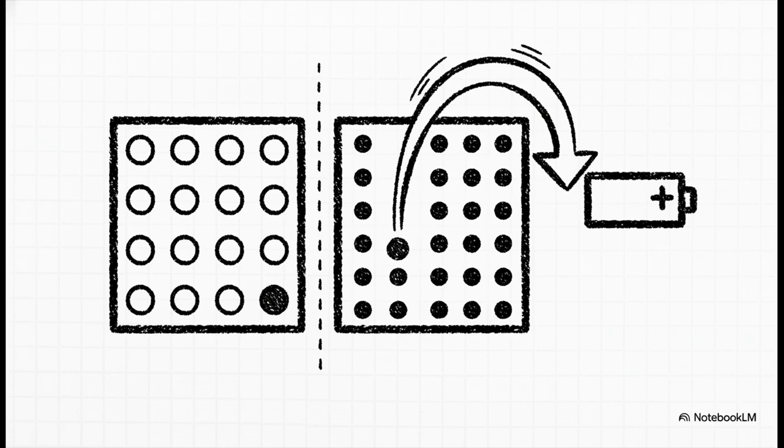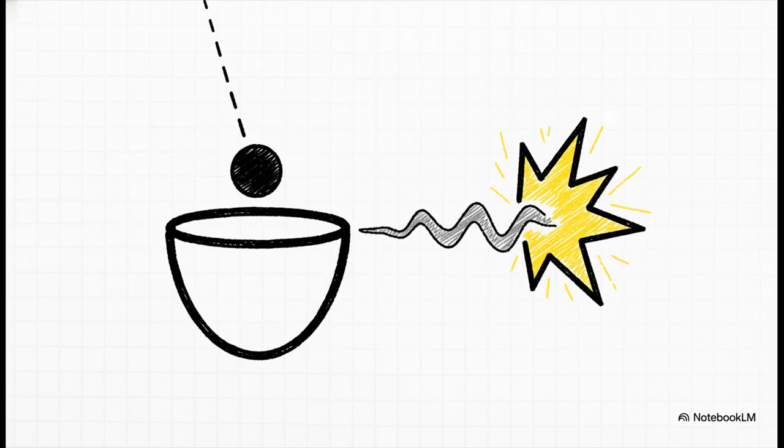This energy essentially forces those highly concentrated free electrons to violently migrate across the junction right into the empty positive holes. And the crucial point here is a process called recombination. As these energetic free electrons transition across the junction and drop into those empty holes, they are forced into a lower, much more stable configuration. Well, because energy cannot just be destroyed, that difference in energy is discharged outward as a packet of light, a photon. Literally every single time your Arduino blinks, you are triggering billions of these microscopic quantum drops.